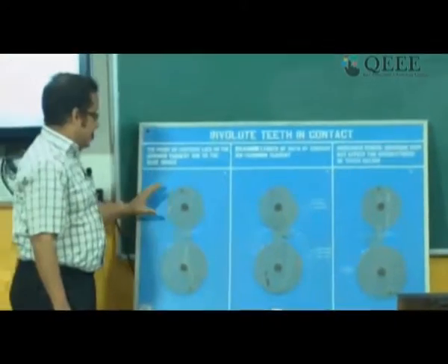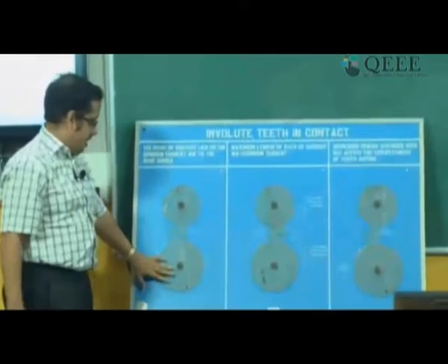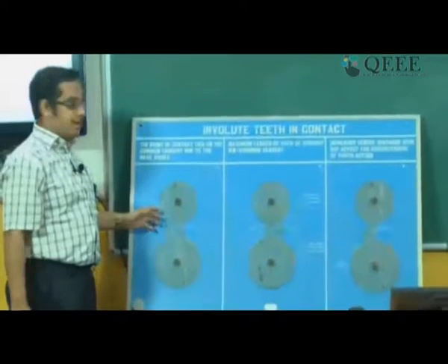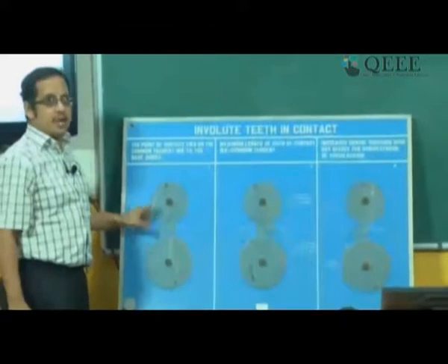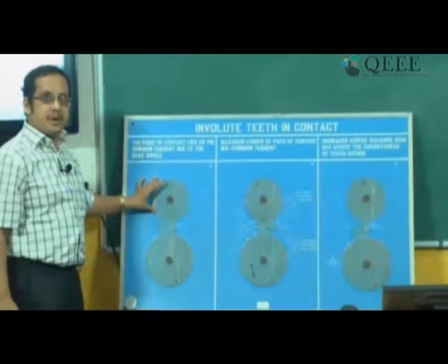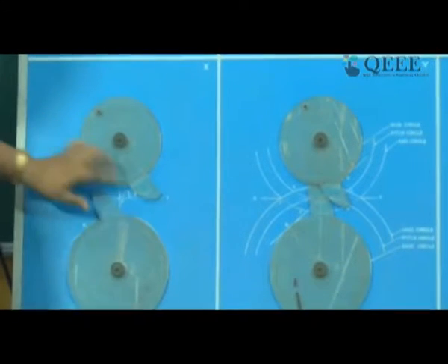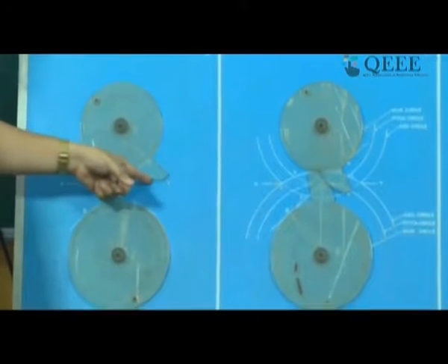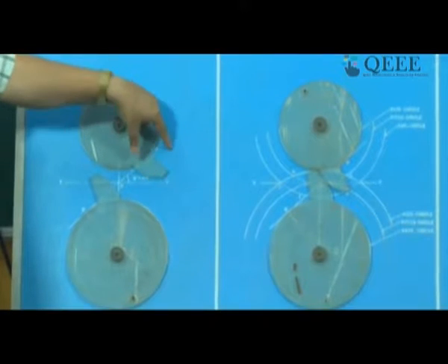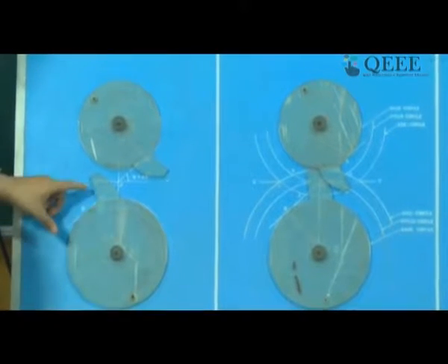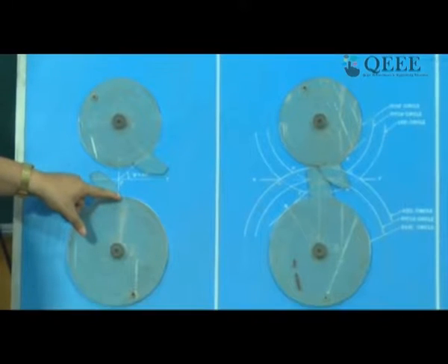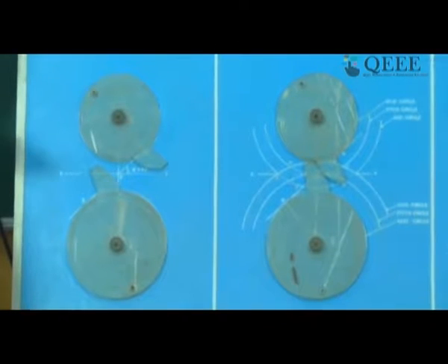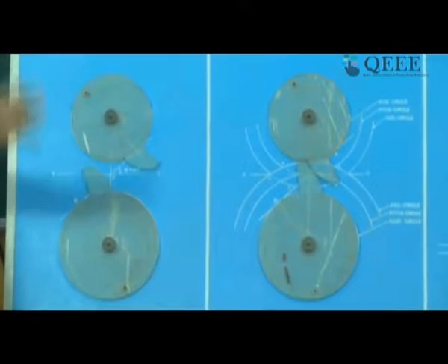What you see here are gears, except that we have not cut out teeth for the entire gear disc. There is only one tooth that is cut out, just for our demonstration purposes. Now you can distinctly see that a gear tooth profile has been cut out. This is the tooth profile on one side of the gear. We have not cut out the other side. Similarly, on this disc you can see a tooth profile. It so happens that it is an involute, but we will come to the mathematical definition of involute and all that.